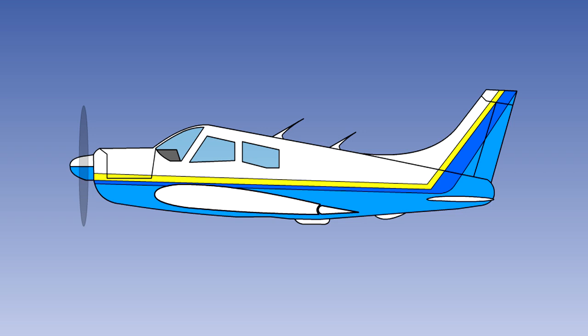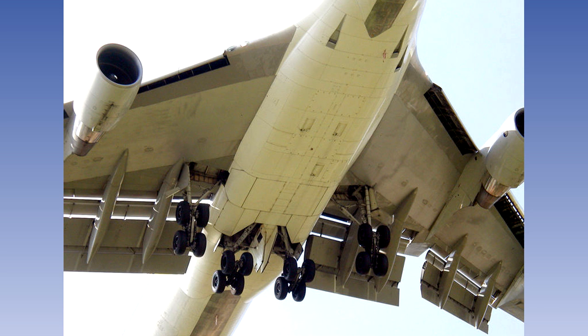The most popular type for light aircraft is the plain or camber flap, with trailing edge flaps, which are a combination of slotted and Fowler flaps, widely used on large transport aircraft. This picture shows the triple slotted Fowler flaps on the Boeing 747 in the fully extended landing position.